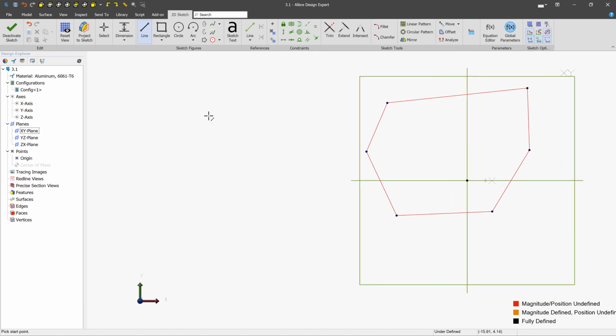A way that you can also end the line automatically without doing that, just in free space, is to double left click. This double left click also works with nodes. So we have the origin, which is a node here, and it doesn't have a figure attached to it, for example, a line. So normally, if we left click that, we're going to continue to get the line tool. But if we double left click on the node, it will end.